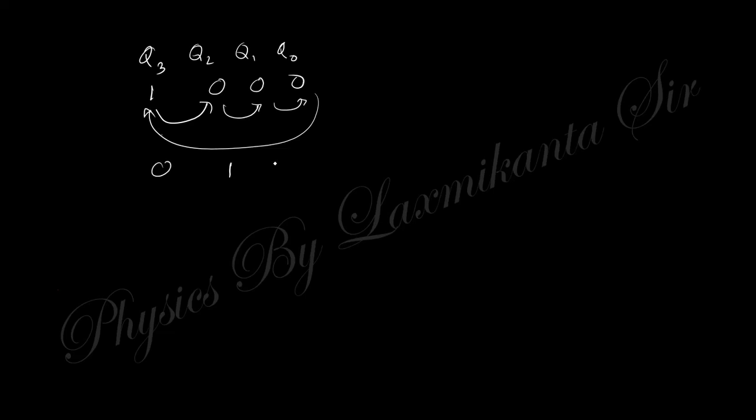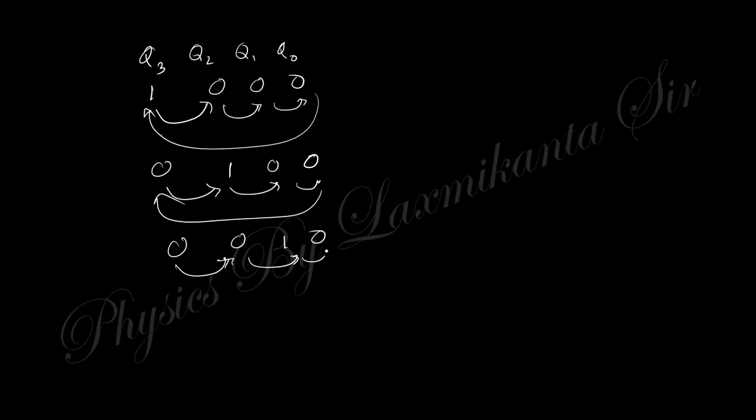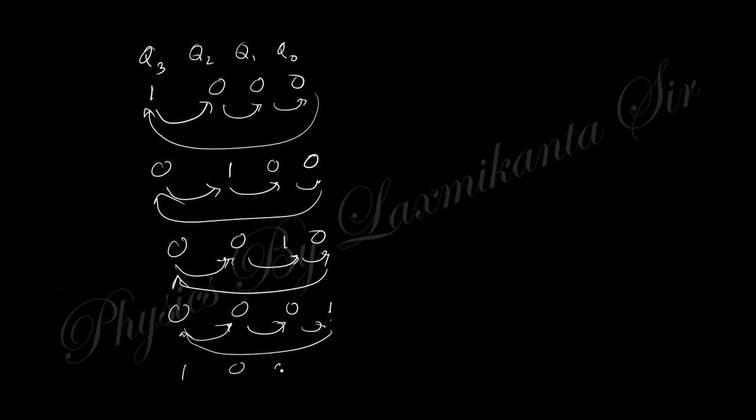So you will get 0, 1, 0, 0. Then it transfers here, and this here. So this is 0, 0, 1, 0. And after that this here, this here, this here and this here. So 0, 0, 0, 1. Again it repeats here. So you will get the initial state. So finally you will obtain the 4 states. Here the 4 bits means 4 states, that is mod 4.